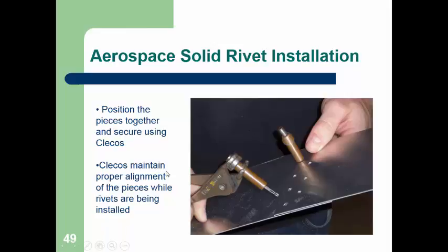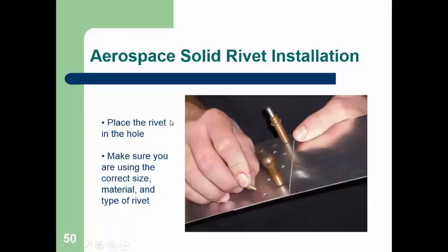And the holes have to be good and clean in order to make that happen. The whole idea of Cleco fasteners, that is, they're temporary fasteners that fit into the holes to pull the pieces together so that you can fasten other parts, other holes.